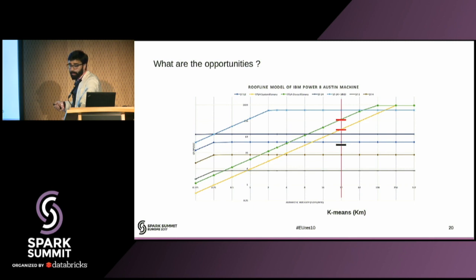And the assumption is that the accelerator design which I have proposed is accessing all the data from the system memory, which means over the CAPI interface here. And if you now change the assumption so that some of the data is stored in the FPGA memory, which is attached directly to it and has a higher bandwidth compared to the CAPI, you also get another jump here as well.